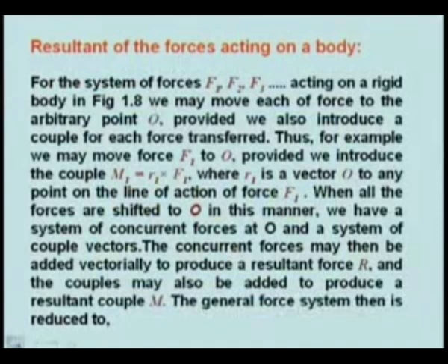So, we may move each of the forces to the arbitrary point O, and we introduce a couple for each force transferred.